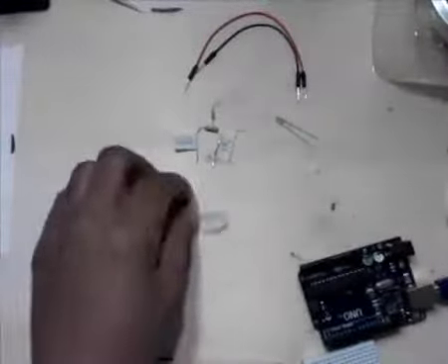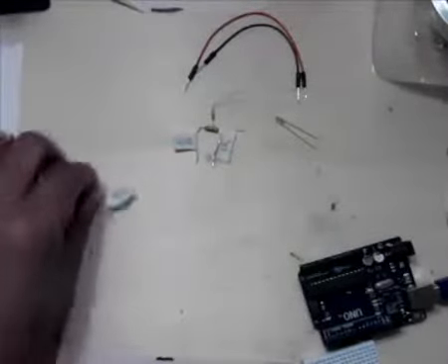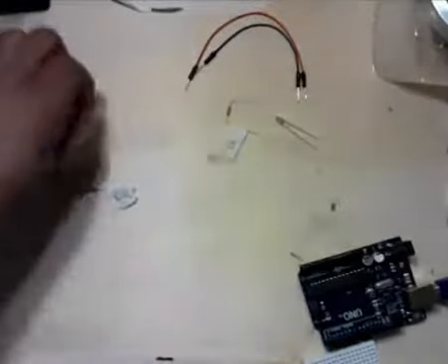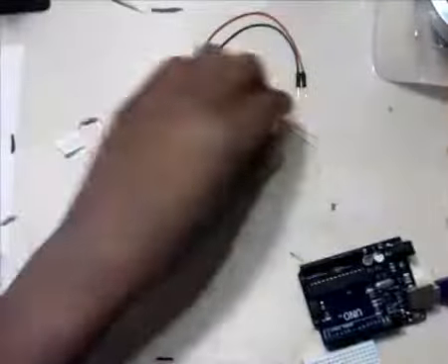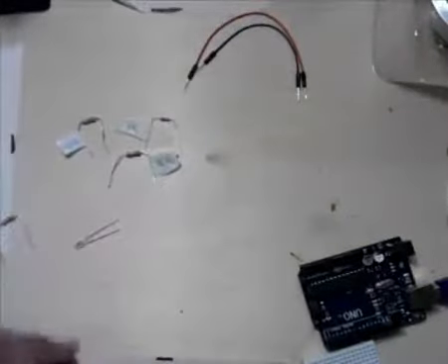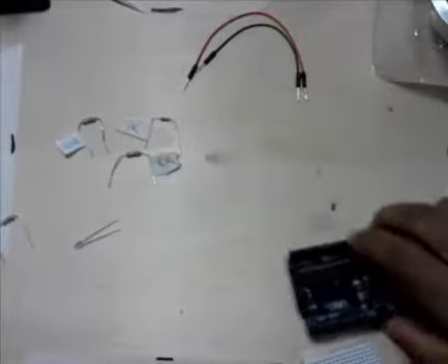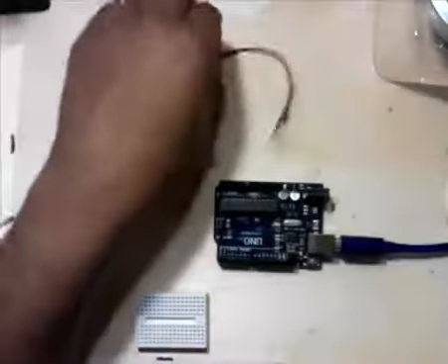when you are working with LEDs, you need to use the right kind of resistor. Okay, this is a 10K, this is 320, this is a 1K. This is the LED that you're protecting with these resistors. Because if you actually try to add an LED without a resistor, it's going to blow out the LED.